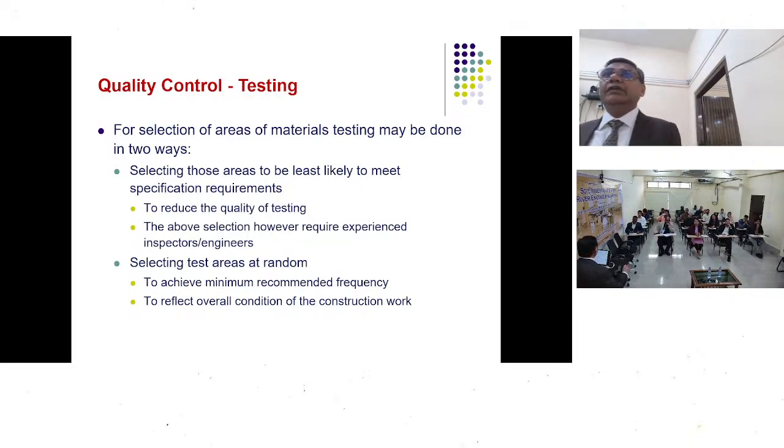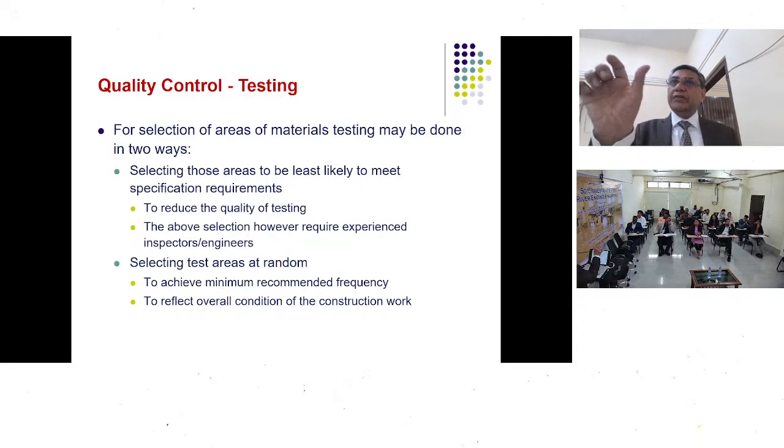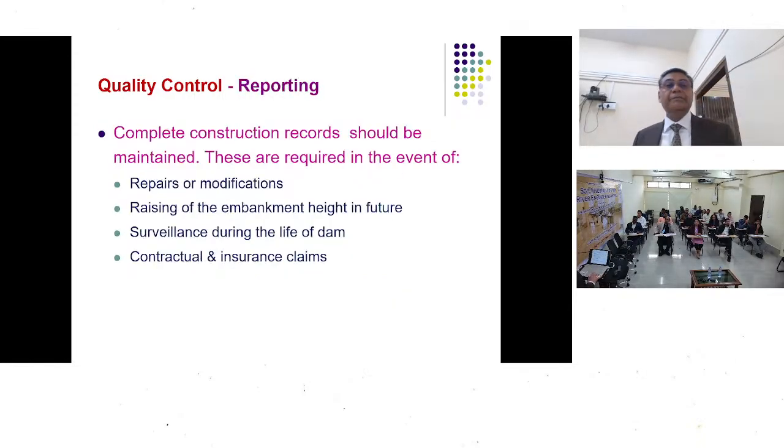So that finally we are getting a thing which is really serving its purpose. So minimum frequency has been identified. So your experience becomes very important there. Then reporting. Complete construction records should be maintained. These are required in the event of repairs or modifications, raising of the embankment height in future, surveillance during the life of the dam, contractual and insurance claims.